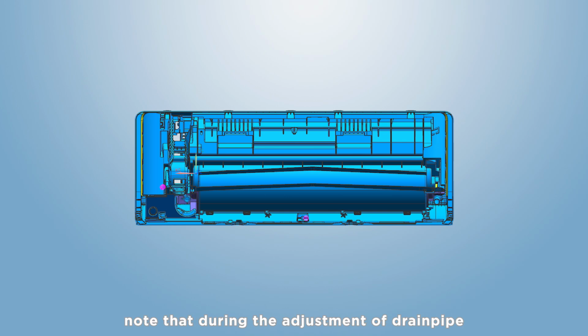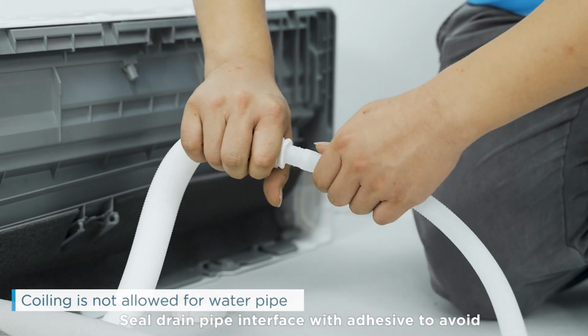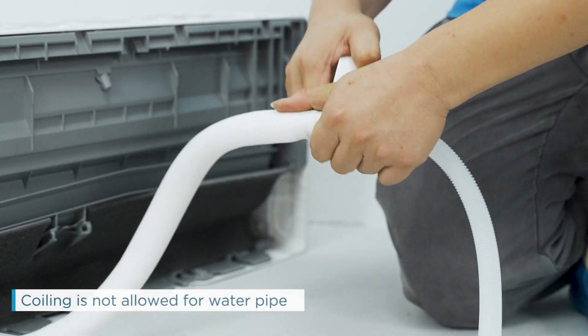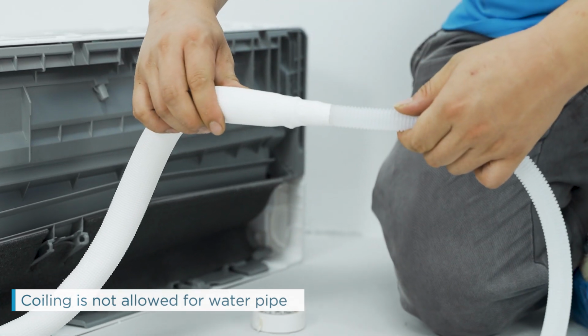Note that during the adjustment of the drain pipe, unused interfaces should be sealed by rubber plug. Seal the drain pipe interface with adhesive to avoid loosening and leakage. Coiling is not allowed for water pipe.